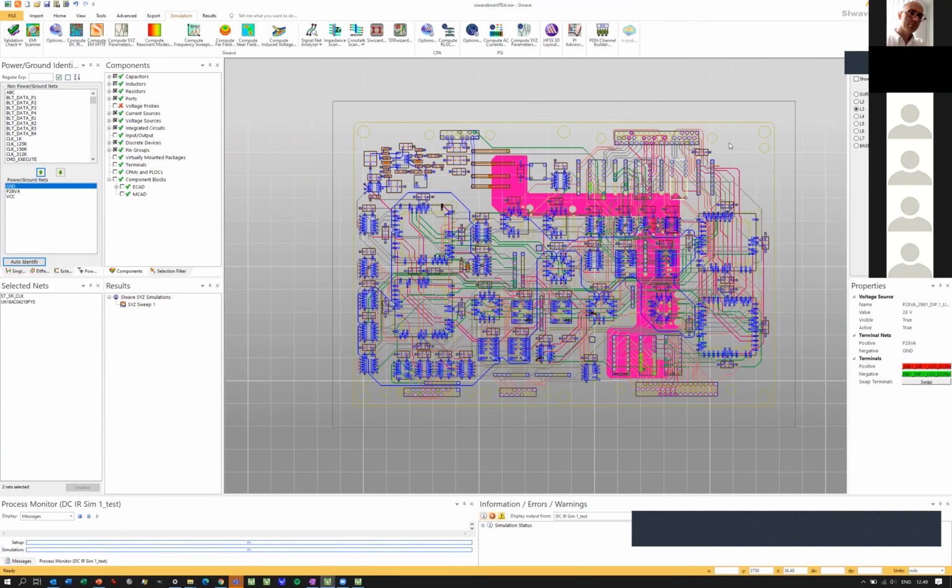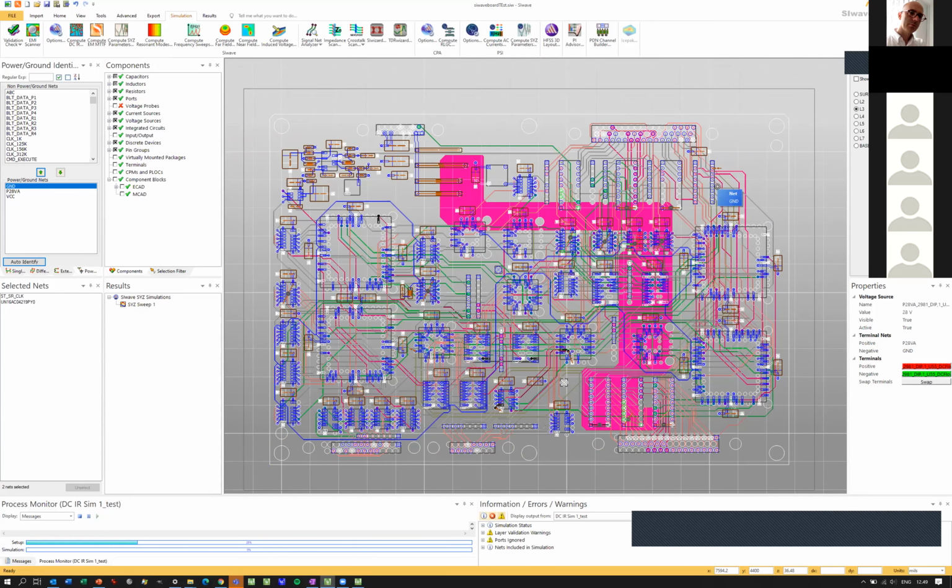Now it's doing the calculation. And typically this takes minutes or something. So, because of the simplification of the CAD geometry as a circuit board, we don't need to do full 3D and we can speed up calculations a lot. Why are they doing this? Okay, easy to understand. S-parameter extraction of the circuit board, and you can get the S-parameter file and put it in SPICE and do SPICE simulations.